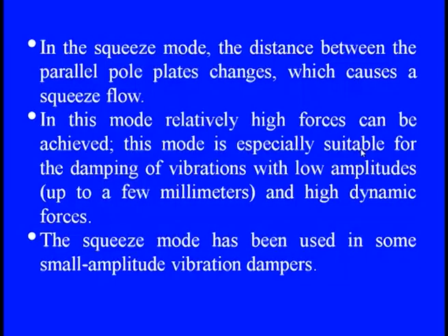This mode is especially suitable for damping vibration with low amplitudes and high dynamic forces, because we know that even when we are going up to only a few millimeters of amplitude, the forces are quite significant, and this squeeze part can effectively absorb the energy. The squeeze mode has been used in some small amplitude vibration dampers because of its operational features.